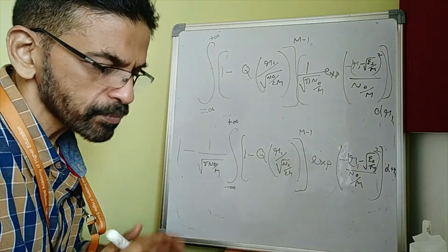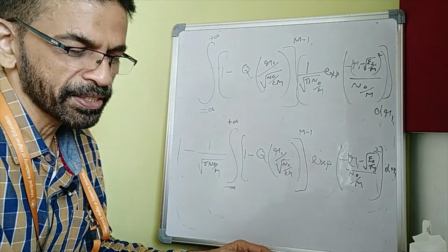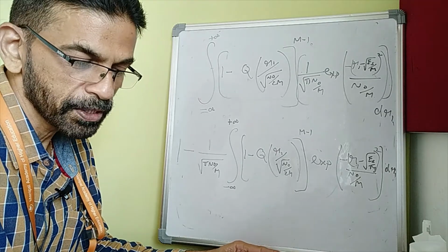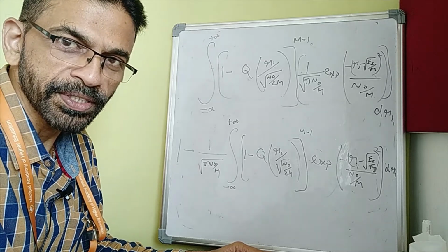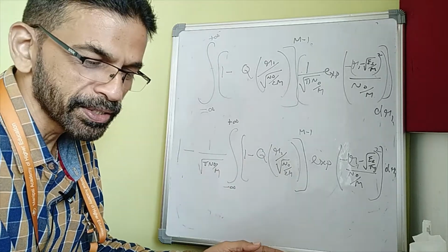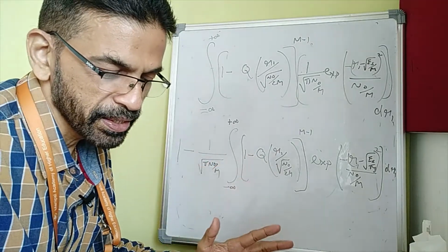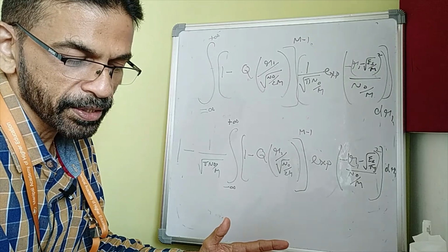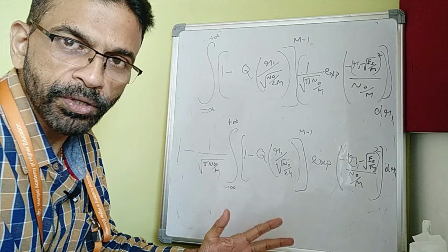Now, without going into the details, you can easily appreciate the fact that we would have ended up getting the same result if in the first place we had assumed that S1T was the transmitted signal. You can rework the whole thing and see. It's not necessary because of the symmetry that exists and the similarity that exists, because of the fact that the noise which is corrupting these signals is independent of the signal.